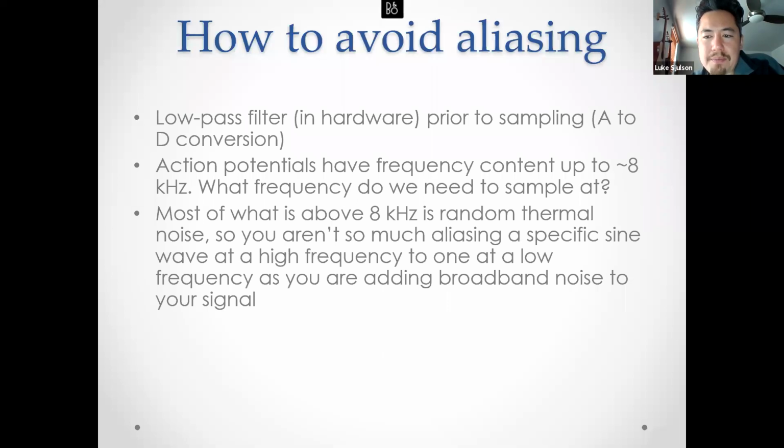What I would say in practice is that when people do recordings, when they want to look at action potentials, say intracellular recordings, or some sort of extracellular recordings where you really want to look at the spike waveforms carefully, then people sample at like 40 kilohertz or 30. People do more regular extracellular recordings where the spike waveforms aren't quite as important, and you sample more than 20 kilohertz, so you save disk space. But you wouldn't sample below 20.